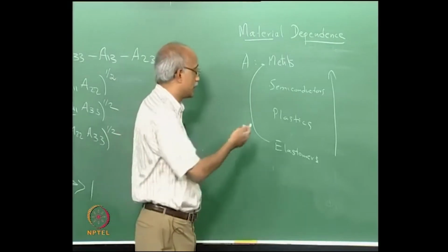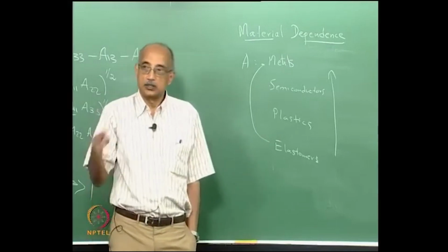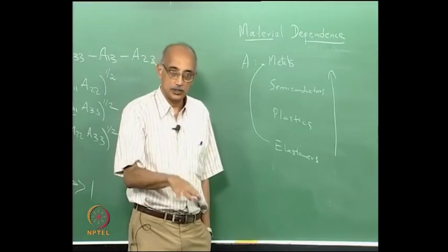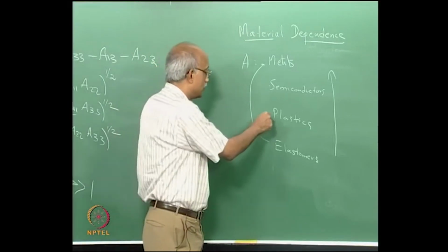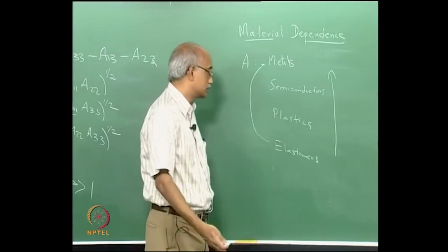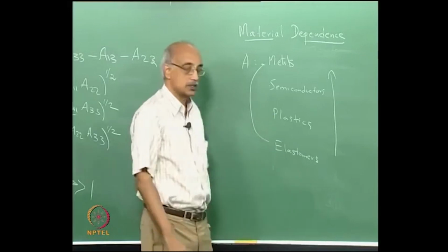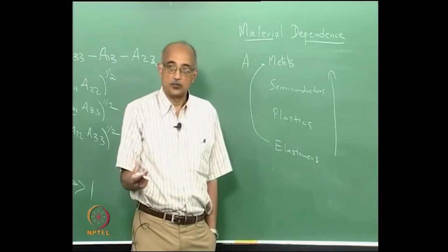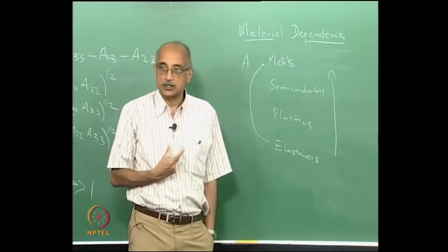So for example, polymer coatings on metals are typically employed to reduce their surface energy, to reduce their Hamaker constant, to reduce their van der Waals forces. How do you reduce the surface energy or Hamaker constant of a plastic? Well, the harder the plastic, the more energy that it has, or the higher the Hamaker constant that it has.